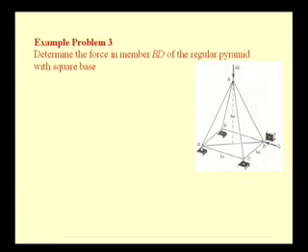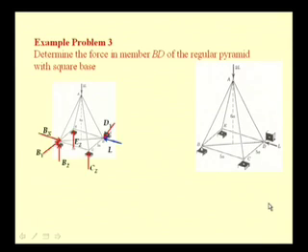First, let us see if this problem is statically determinate externally. In order to do that, we have to construct the free body diagram of this truss. Since at B the truss is pinned, it arrests all translation and thereby provides 3 components of reaction Bx, By and Bz.